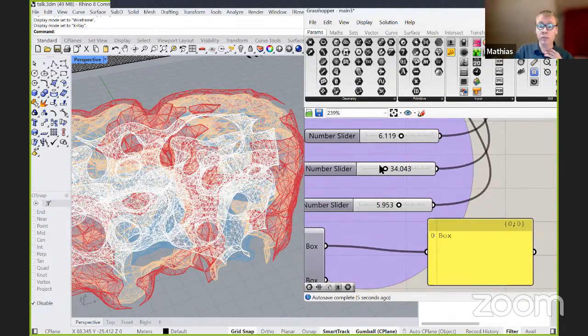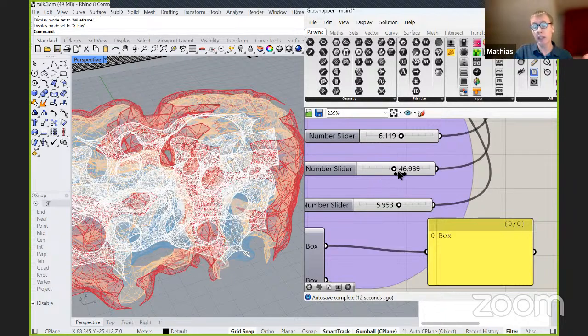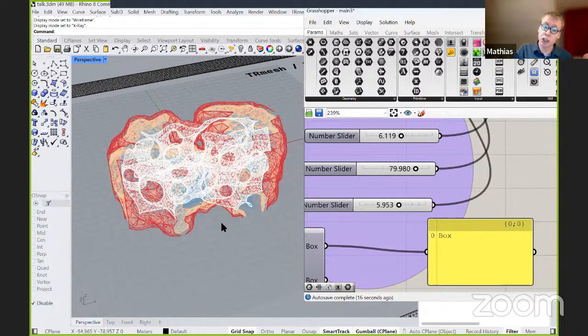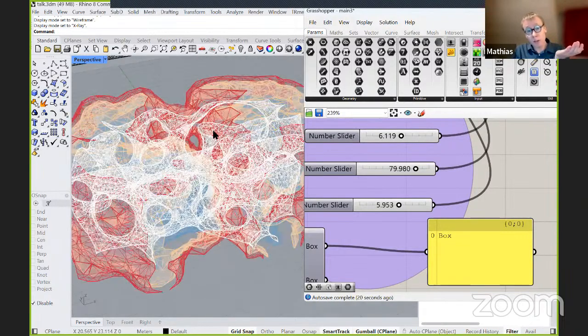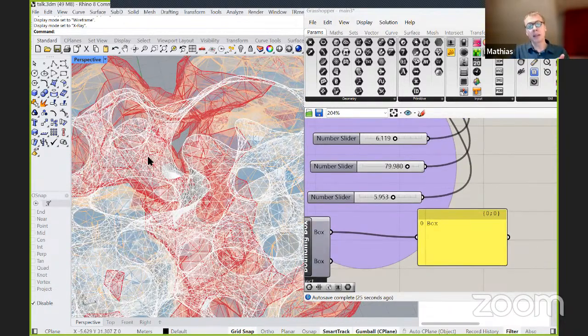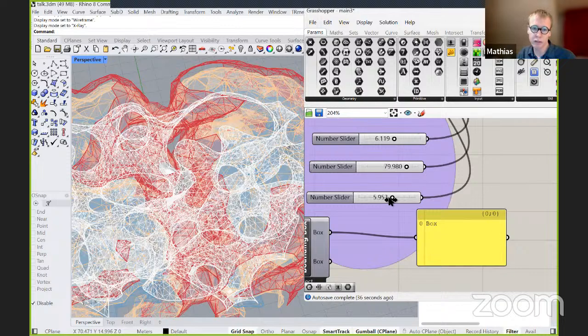So if you want to apply this workflow to, say, an engineering part, then ideally you apply Shrinkwrap to obtain an initial mesh around your ground truth mesh. And then you apply this methodology here, the TRmesh methodology, to the closed volume that you obtain by Shrinkwrap. All right, so that would be the perfect way to apply this.